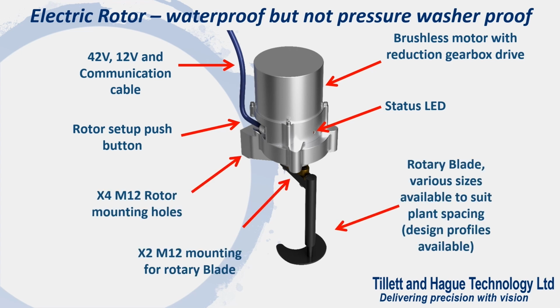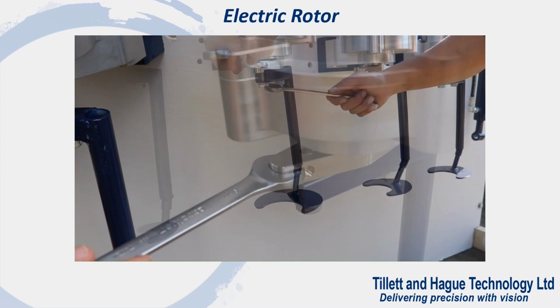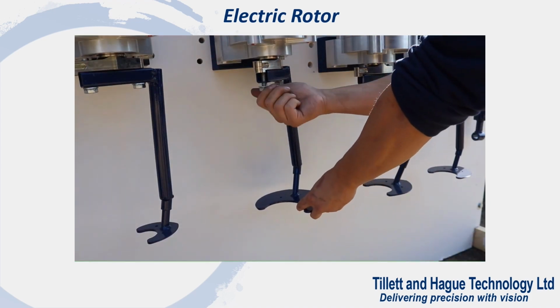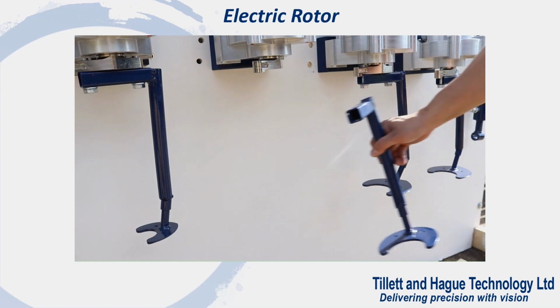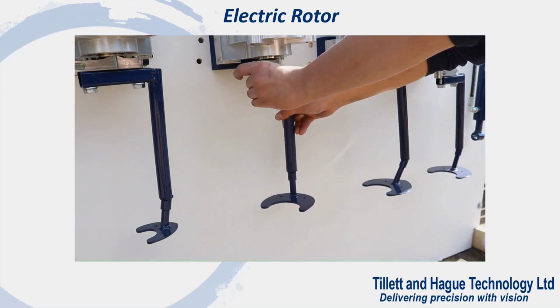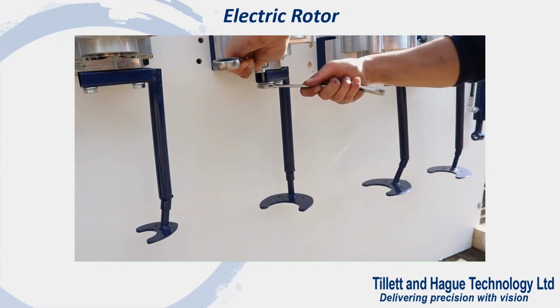Rotary blade profiles are available to cover a wide range of crops, though it's often possible to use one compromised blade profile to cover a range of crop sizes. Rotary blades can be easily changed for different crop situations, using standard 90mm tools, as shown here. Later in video 4, we will explain how to choose a correct cultivator blade for a given situation, and to set the rotors up on a machine.